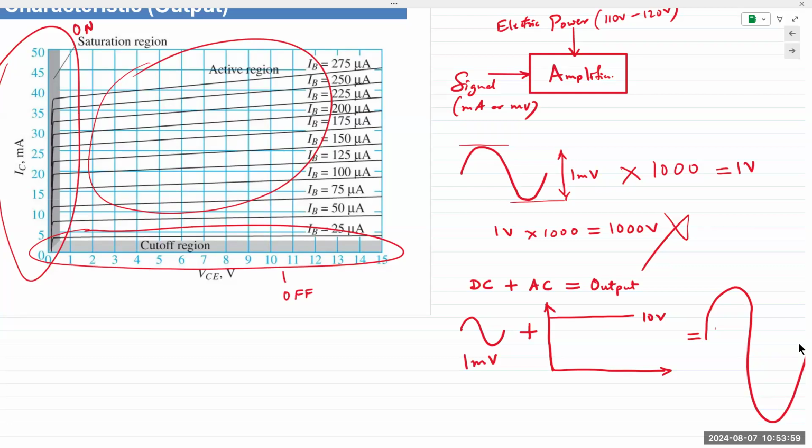And that's the hardest concept for first-time students. I mean, not just non-EE majors, even EE majors. This is the hardest concept to grasp. It's not coming out of thin air. When we say that the base is controlling the current flow, meaning if you apply any sort of signal to the base, it is giving the shape of that incoming signal to the external DC bias that is applied to the transistor, and hence it results in an amplified output.